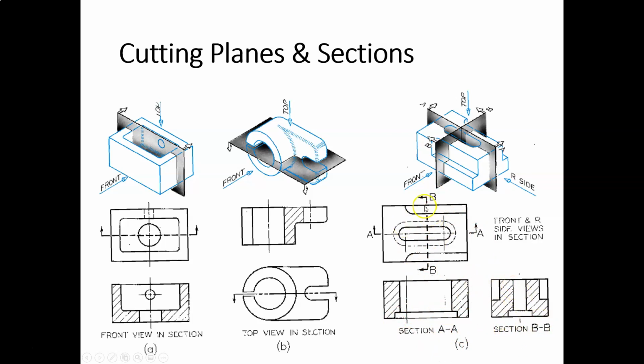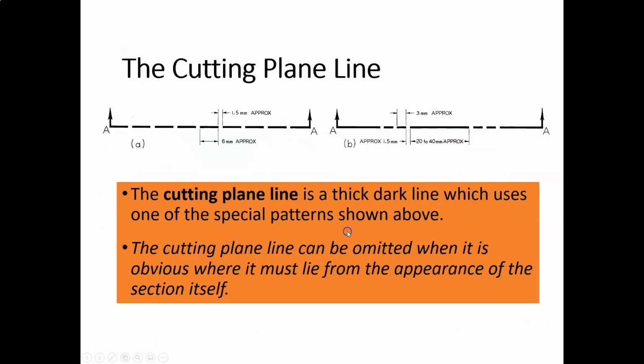Notice that BB is kind of around the corner here, so to speak, right? So it's a right side section view, but it's developed normally from the front view section. Obviously, alternately, it could be placed up here, but you would have to rotate it 90 degrees counterclockwise, and then of course make sure it's aligned. Section views are aligned the same way that orthographic views are aligned.